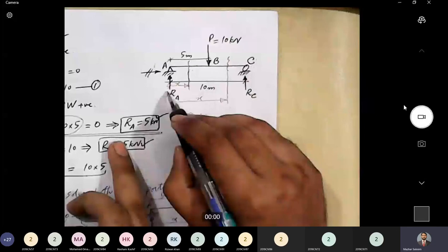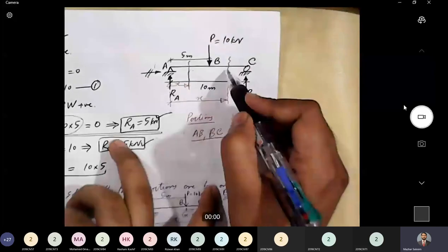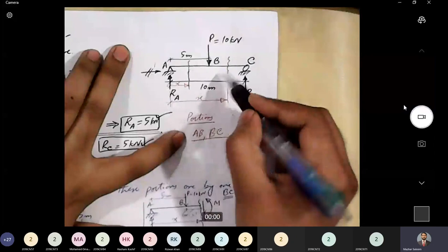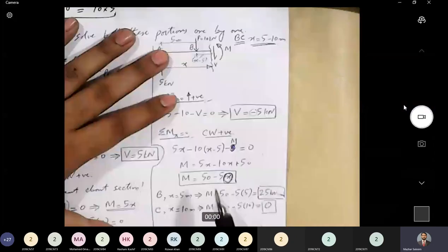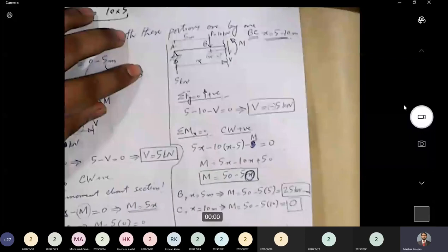And as the situation is changing, like if I look at the condition of applied loads, it is changing from AB to BC. That's why this equation of shear force and bending moment that I have written here is just valid for section BC. It is not valid for section AB. So we will not call that ABC. This equation is valid just for BC. For segment AB, there is another equation that we wrote previously. But this equation is just valid for BC.